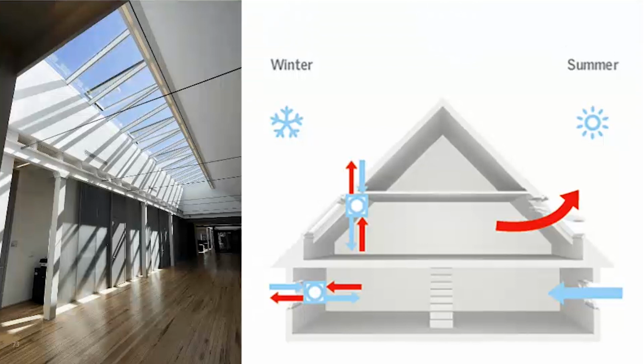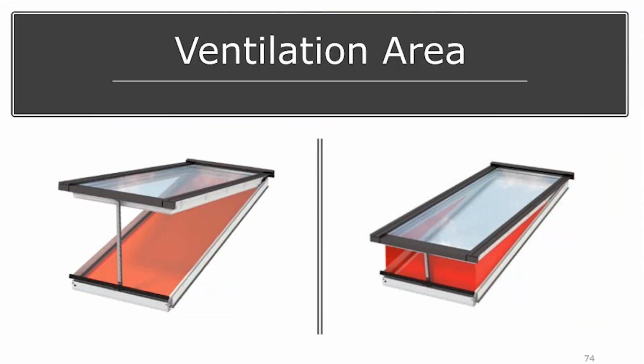We've seen an increase in interest the last few years of doing combination ventilation. So with smart buildings, you have the ability for the building to know, are the outside conditions good enough to open up the windows and bring some fresh air through? Or should we be using our mechanical ventilation at this time? When we're working with these companies, as the HVAC designers doing these systems in support of the architects, we usually have to give one of two ventilation areas. There's different ways to calculate this, so we have these numbers available to provide to the mechanical designer when they're doing the ventilation system.